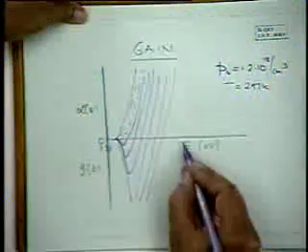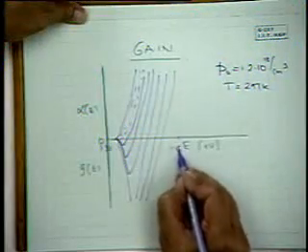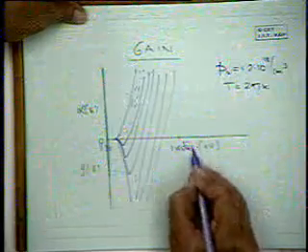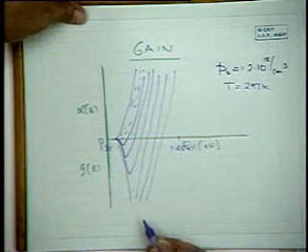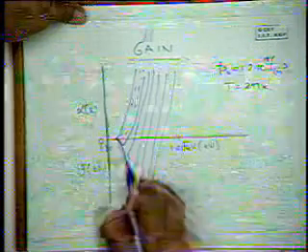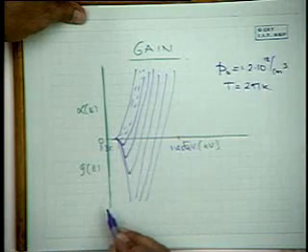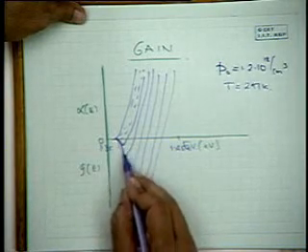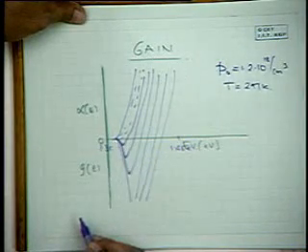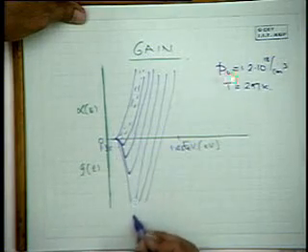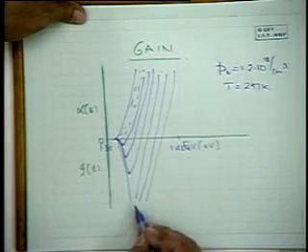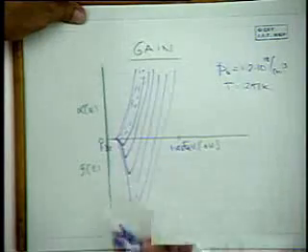And say here is 1.45 eV. So what is important in lasers is the energy at which this peak occurs, the maximum gain. The laser will tend to oscillate at that energy, and what is the magnitude of the gain. If the magnitude of the gain is very large, it will overcome the losses, and the threshold current will be lower.